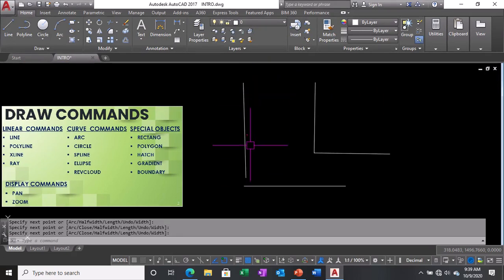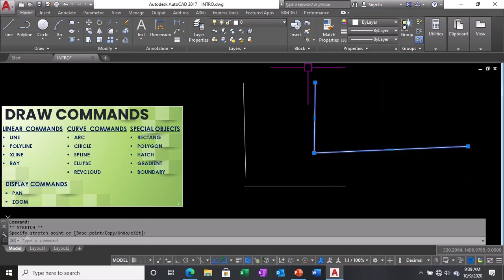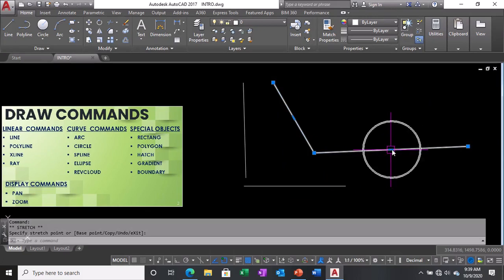When you create objects out of line objects, each segment is an individual object. But for polyline, even if it consists of 100 segments, isang object lang po siya, or ang tawag sa AutoCAD, polyline entity. Okay? So, when I click this, or when I pre-select it, meron din siyang grips, but may difference po sila. Although on both ends, you can stretch and you can lengthen, the middle grip differs from the other. Okay?